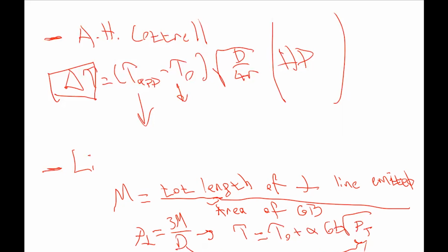All right. How about nanocrystalline materials? Nanocrystalline means these materials with the grain size less than 100 nanometers. Are they very strong materials? They can be viewed as composites consisting of small dislocation-free crystals in an amorphous matrix, and the grain boundaries are on the order of 5 nanometers in width.